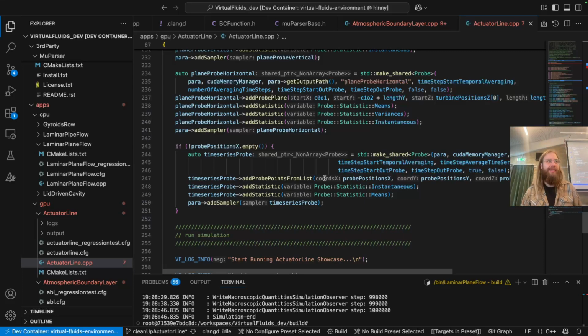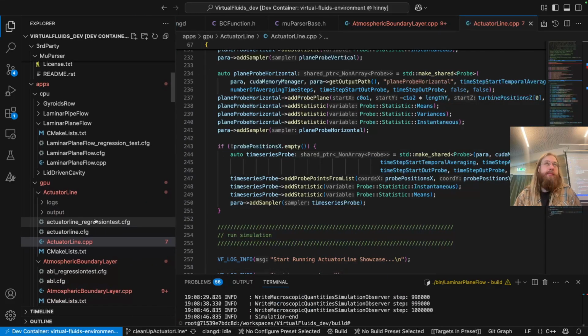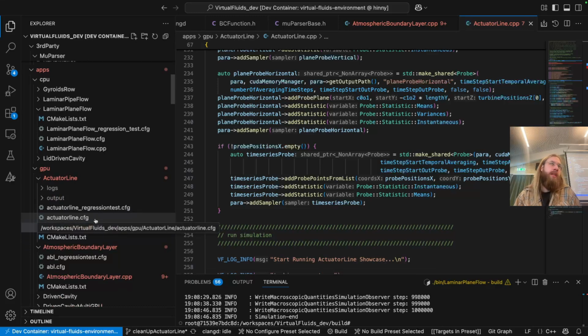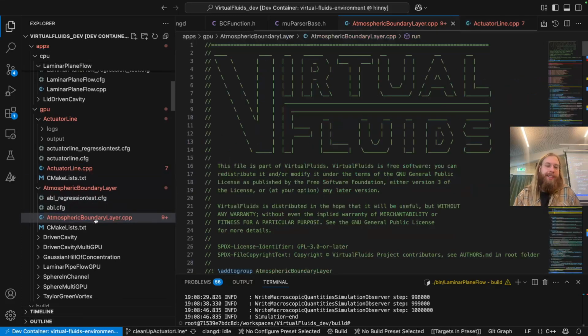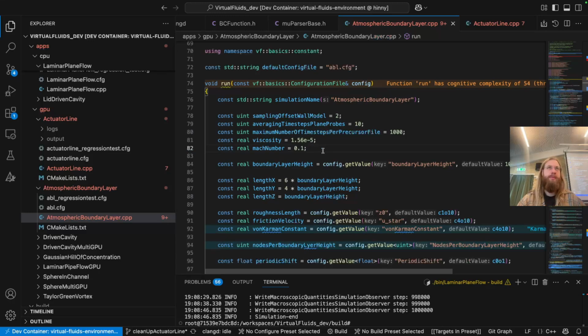Okay. Also, you don't know how far the log law is valid. It's not valid throughout the whole domain. It's a matter of which one is more accurate or less wrong. Our way is much less wrong. What you're describing is a bit similar to the first way that a wall model was implemented in LBM, which is the Malaspinas and Sagaut paper from 2014. They reconstruct the entire population on the wall. So there are models that are similar to that. I think for our case, ours works better.